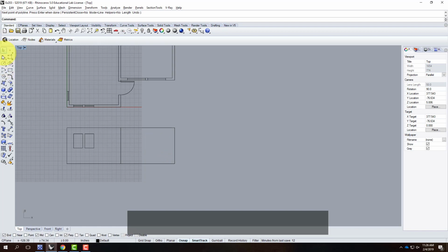So I'll do the same thing. I'm going to use my polyline. I'll start at each window, and I'll come down and I'll draw a line segment. Actually, it would be better to use smart tracking. I'll come down from that line until I intersect. Oh, didn't quite do it. There it is.